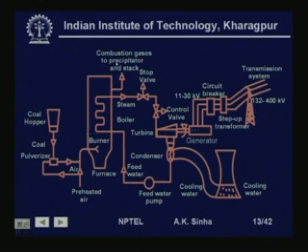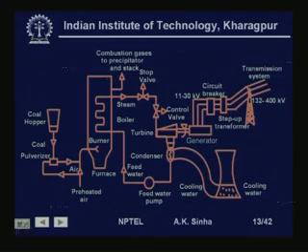Now, in order to reduce the pollution, because the flue gases will also be carrying a large amount of unburned coal in very minute particles, you will see the older stations might be giving you some black smoke, but the newer stations have electrostatic precipitators which basically scrub out all these particles in the flue gas, and from the stack you will find a very thin white smoke coming out.